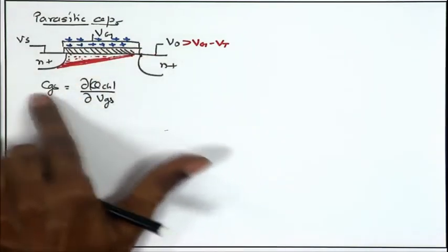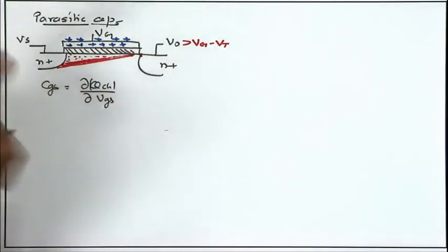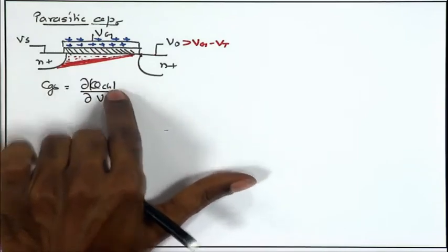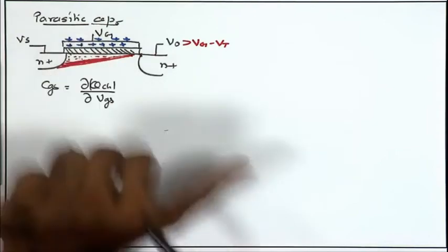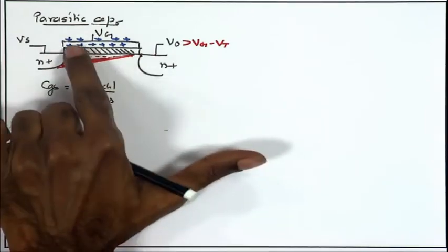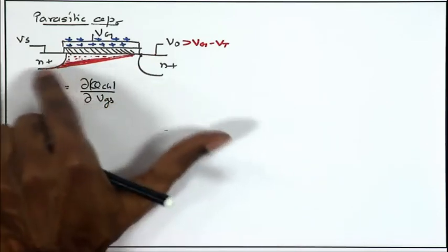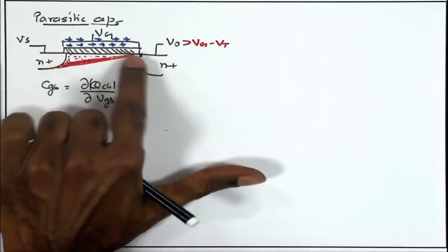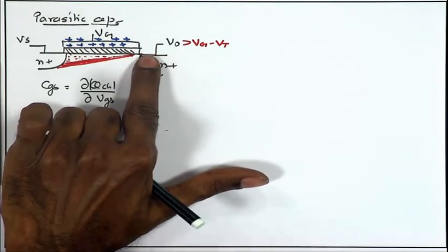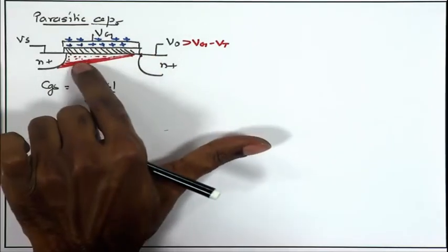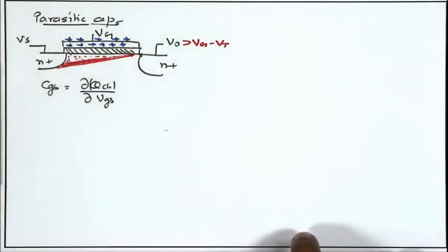Capacitance is a positive quantity. So, if you increase V G S for an NMOS, you get more positive charge on the gate, and as a result an equal amount of negative charge on the channel. If you add delta q positive charge on the gate, you get delta q negative charge in the substrate.